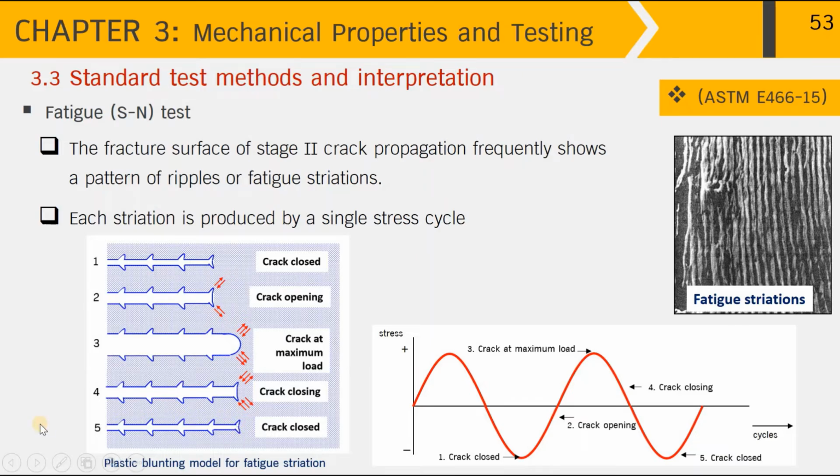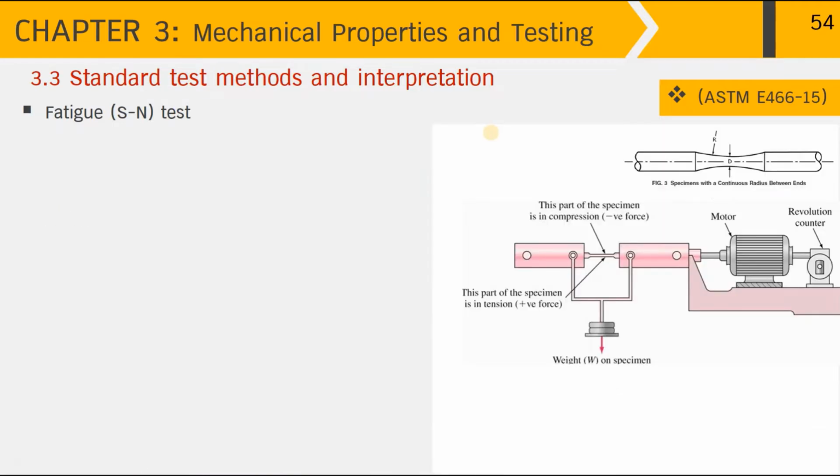So I hope that you understand the nature of fatigue a little bit more. Then let's move on to how to perform the fatigue test. Up here is showing the specimen's dimension with the continuous radius between ends of the specimen. And over here is the diameter of the test sample. And this can be done according to ASTM E466.